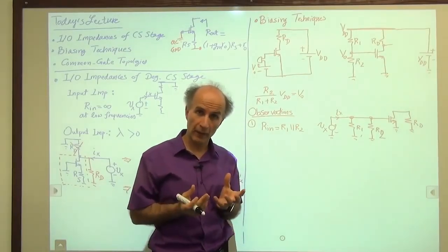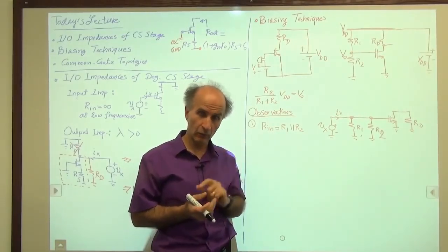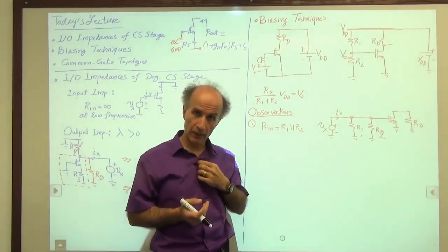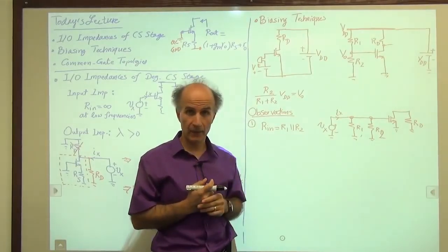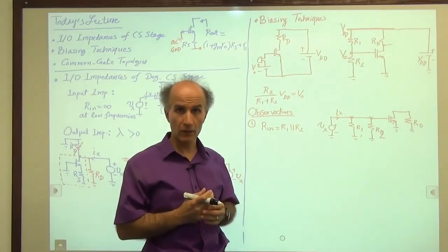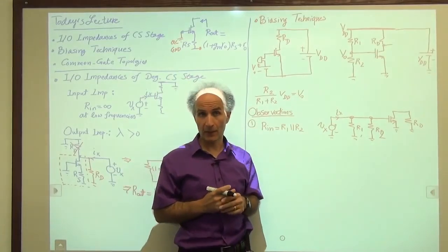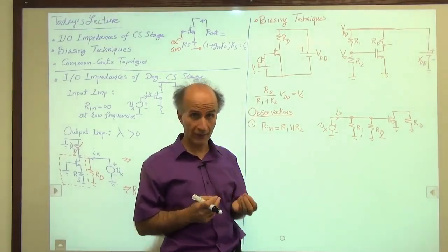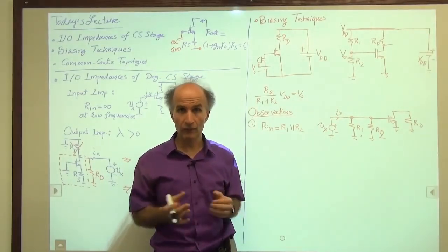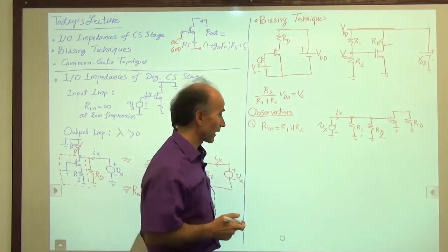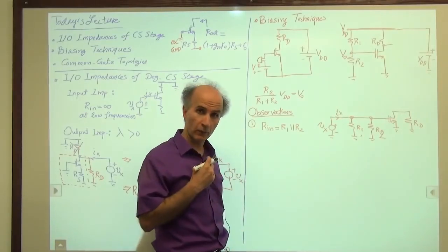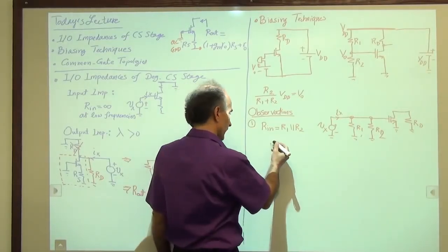A realistic model of a microphone is not just an ideal voltage source. This microphone has some internal resistance. If you remember in basic circuits, when we consider a battery, we said a battery has some internal resistance. It's really a Thevenin equivalent, so there is some internal resistance. So when I try to model the microphone more realistically, this is what I have.